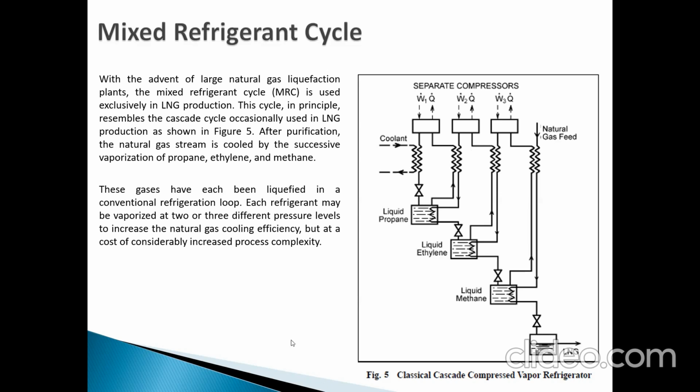These gases have been liquefied in a conventional refrigerant loop. Each refrigerant may be vaporized at 2 or 3 different pressure levels to increase natural gas cooling capacity, but at a cost of considerably increased process complexity. Masyado malamig kasi yan. So, yan, reduce, then reduce nyo naman to. Pababa ang temperature.